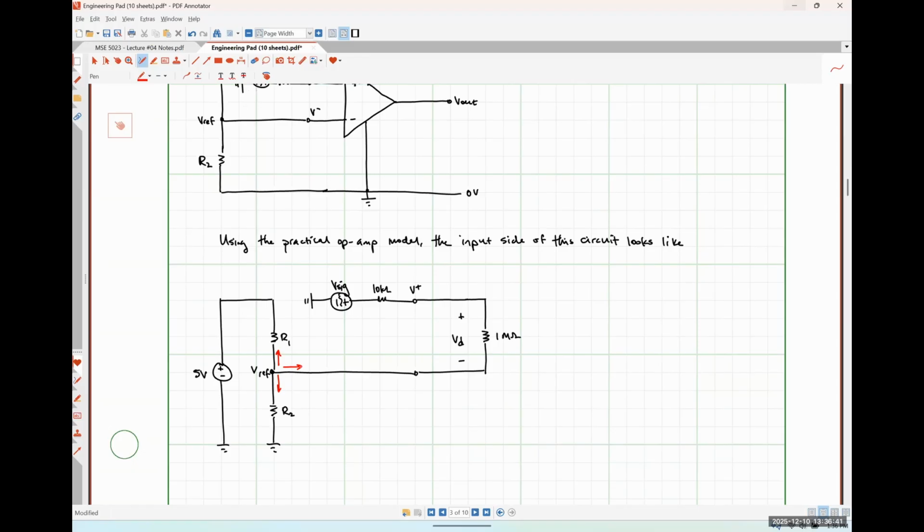Okay. So if I apply KCL at that node, so KCL at reference node, what I'm going to have is (VREF minus 5 volts) over R1, plus VREF over R2, plus (VREF minus V sig) over what's essentially Rn plus R sig, but I'm just going to write this down as 1 mega ohm plus 10 kilo ohms, is equal to 0.